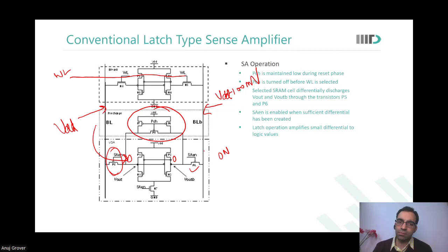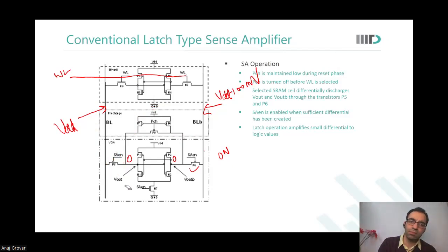Sir, okay, understood. Even if there is a VDD over there, what I understood is that the sense amplifier should be working on a higher voltage than the normal memory voltage. No, it is the same voltage. Okay, so sir, just explain this condition with VDD also, once. Because if I take VDD, then I'll be writing back into my VDD minus 100 millivolt, right? And I am not supposed to connect those both nodes directly because they are at different potentials actually.